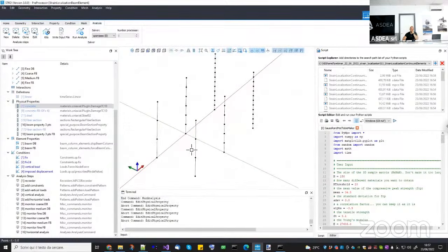As we said, the same problem that we had before, we have it now, we've solved it. If you notice, in this kind of problem, I didn't put any imperfection as I did in the previous model. Why? Because putting imperfection is only necessary if you're doing a simple benchmark problem, which has a constant state of stress. Now, in this case, it is not constant.